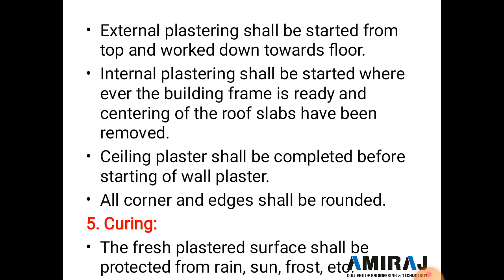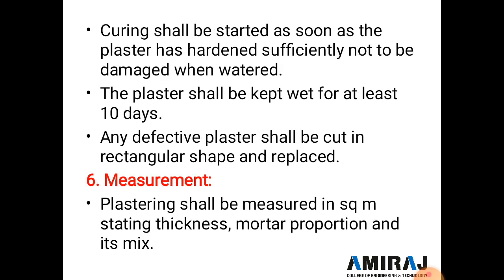The fifth specification is curing. The fresh plaster surface shall be protected from rain, sun, frost, etc. Curing shall be started as soon as the plaster has hardened sufficiently and will not be damaged by water, and the plaster shall be kept wet for at least 10 days. Any defective plaster shall be cut in a rectangular shape and replaced with a new one.